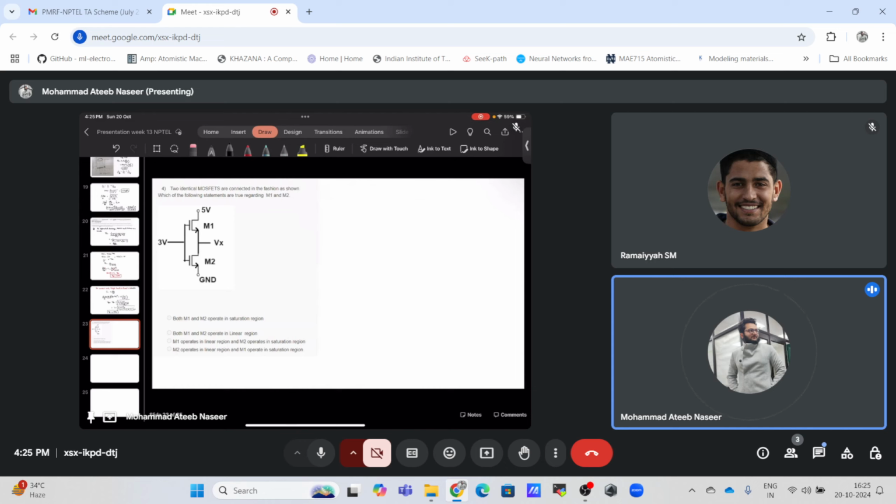Okay, it is only in the triode region, or the deep triode, or the non-saturation region, because now you want the exponential discharge. If you want the exponential discharge of a capacitor, how can it happen? You have derived in network analysis, even in the 11th or 12th standard, that if we take a resistor in series with a capacitor, we will have an exponential decay of the charge. So that's what we have done in this problem.